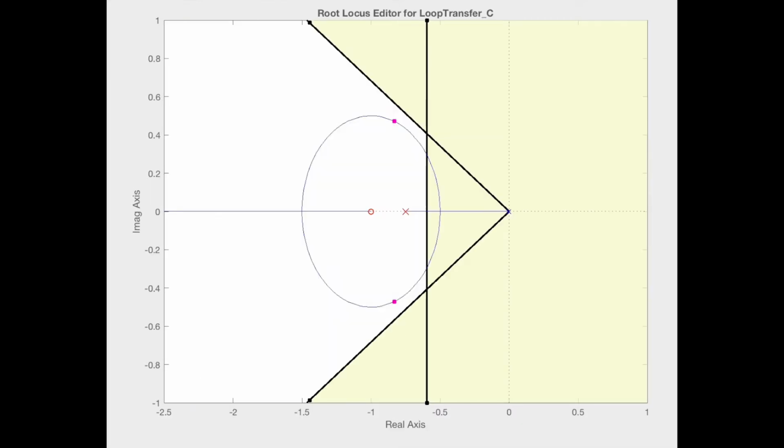To fix the failed root locus, we add our parameters that were calculated earlier for a rise time below 2 seconds, a percent overshoot less than 2%, and a steady state error of 0. For further remedy, we added a real left-hand plane zero and moved it until it was in the correct region. Since we are using a PID controller, this caused issues with having a gain margin of infinity and a non-existent phase margin. So we added another real left-hand plane zero and moved the poles and zeros around until they gave us an acceptable phase and gain margin. The phase and gain margin came out to be 81.9 degrees and infinity respectively.